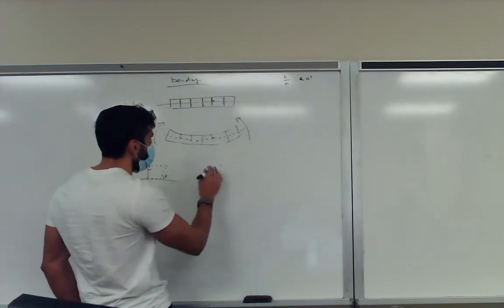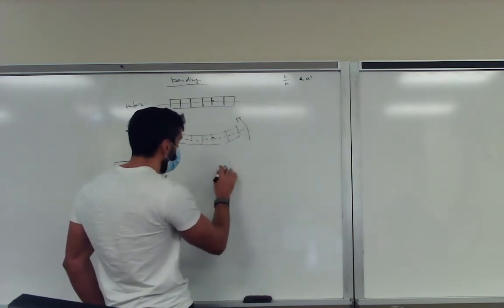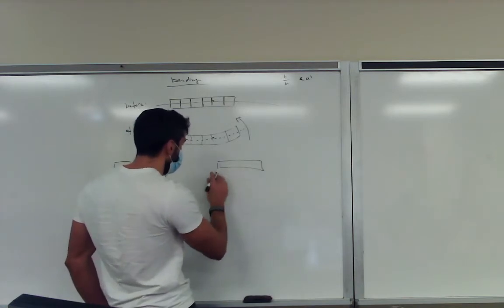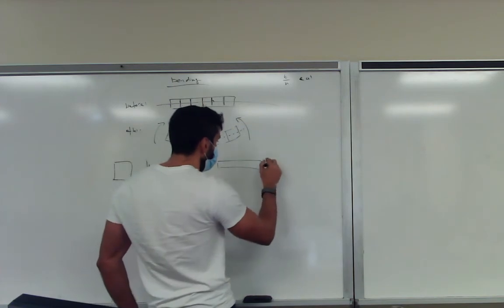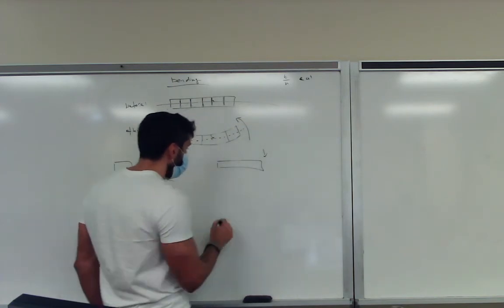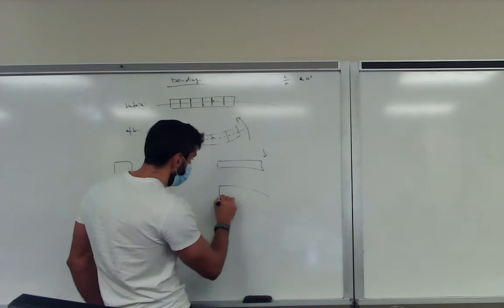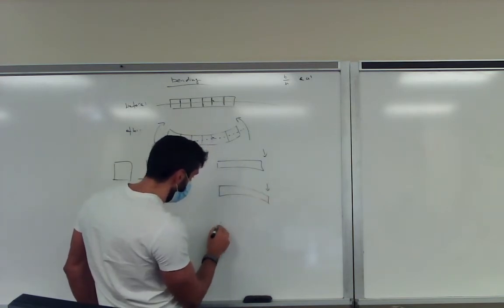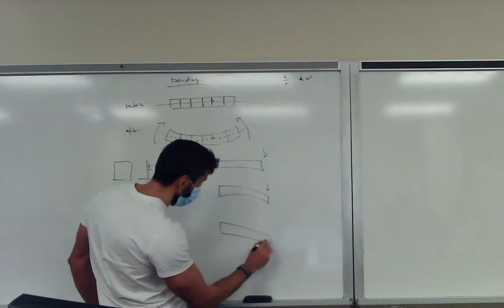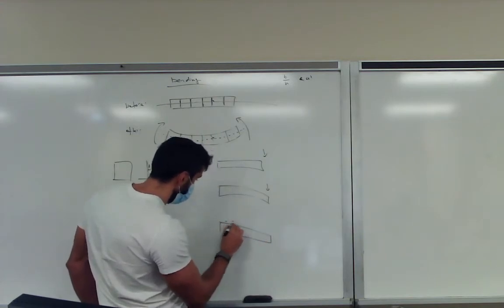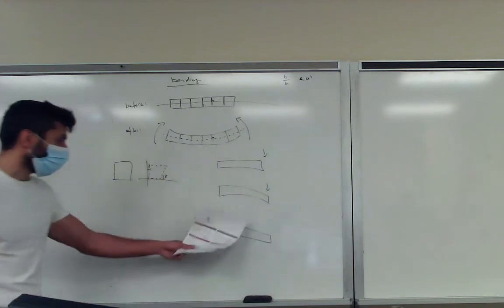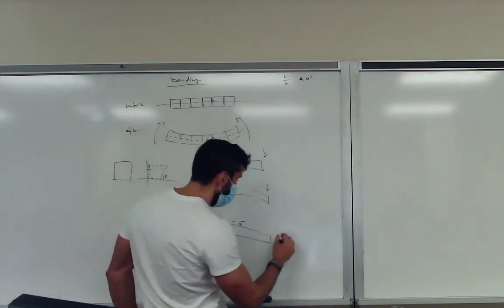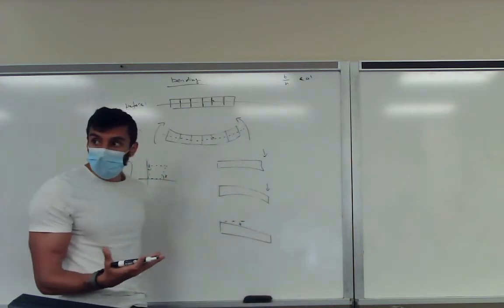If this is the real case, let's do a beam. We basically load it with a force, so we get our normal deflections, and then we also get some shear deflection. This is our shear angle. So the deflection here due to shear, we can use small angle approximations.